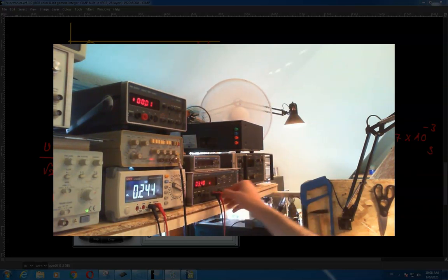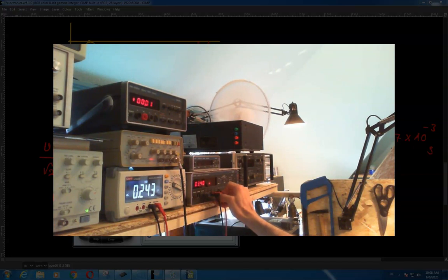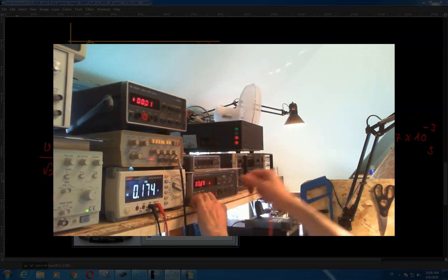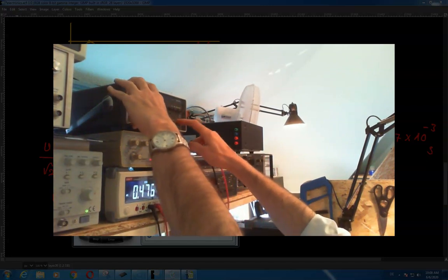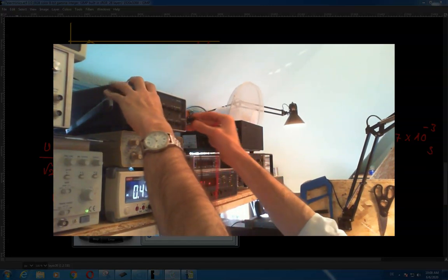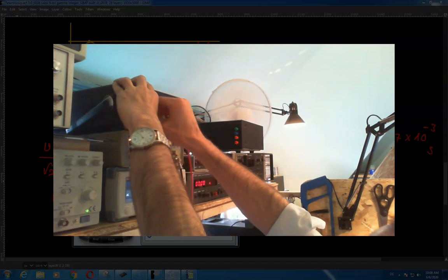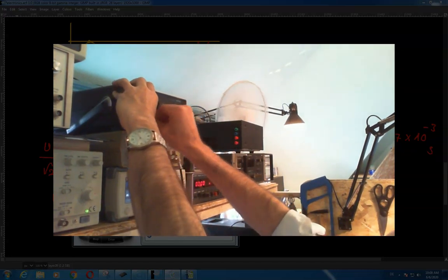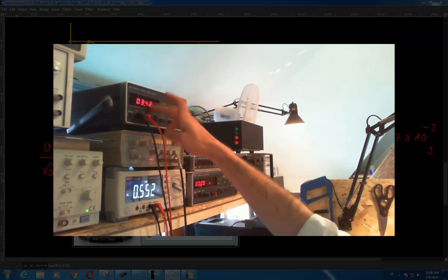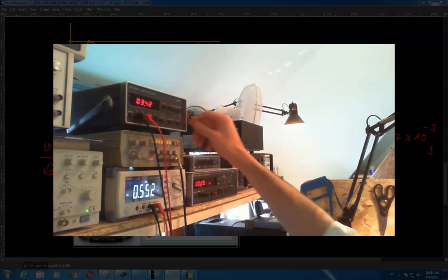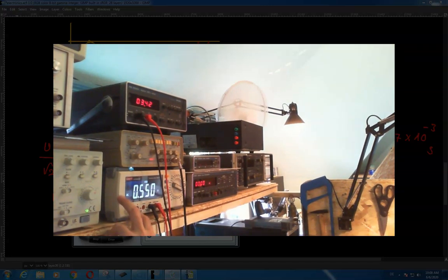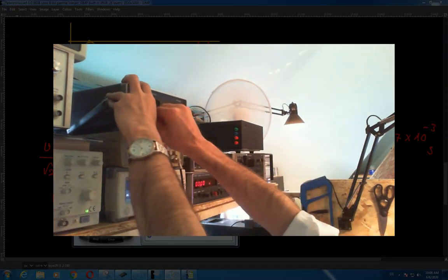And let's even try this voltmeter over here as well. If you try this voltmeter, volt AC, if you connect the negative lead over here and the volt over here, you can see that you can read 3.4 volts on this meter as well. But this meter cannot do that sort of thing. It's just not made for high frequency voltages, right?